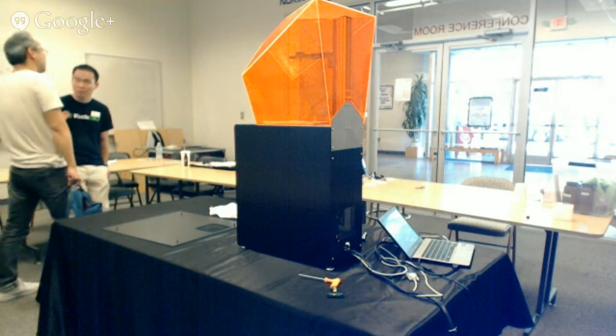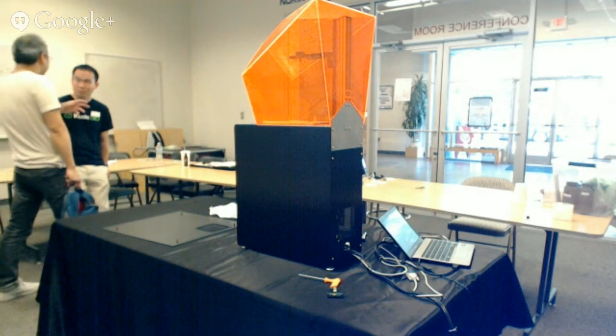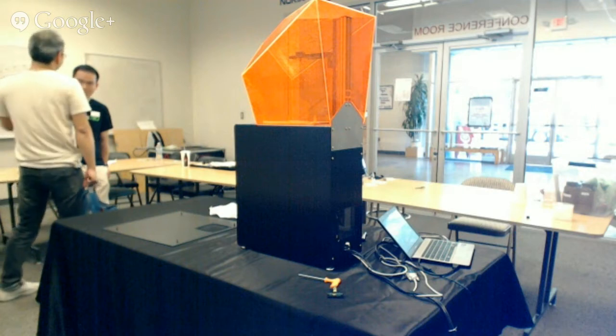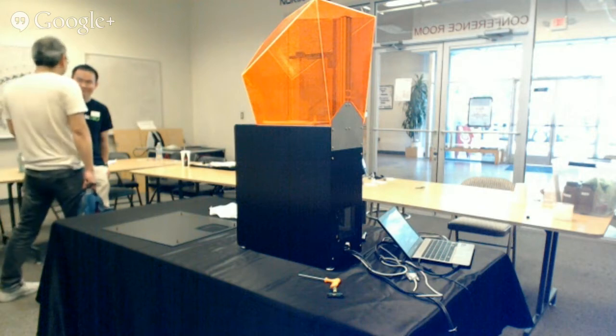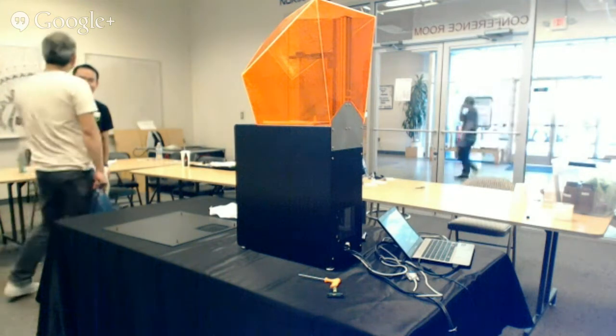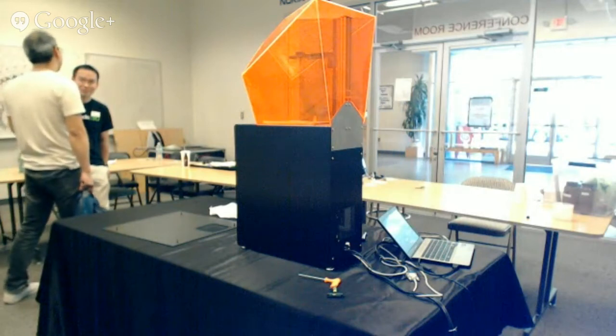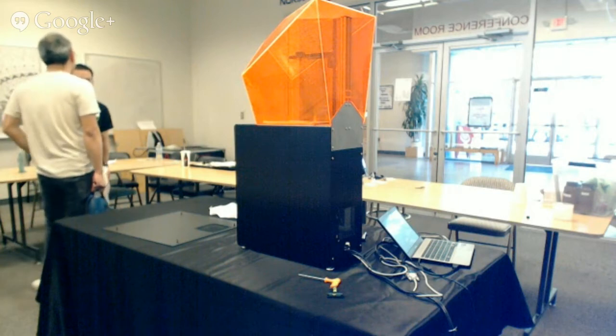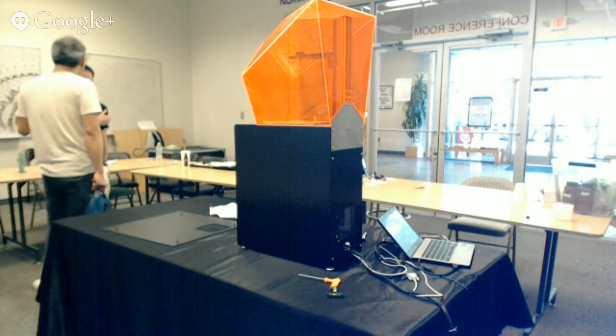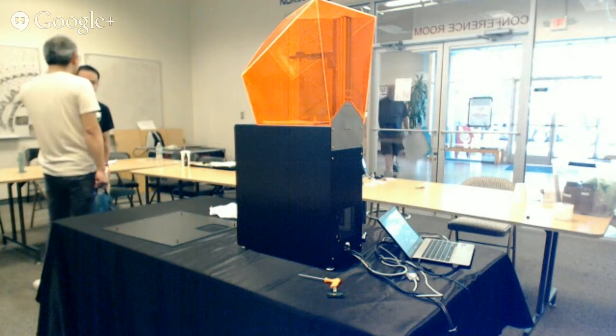Now, if I'm going between 37 and 50 microns, and I know from talking to John that you already had the projector set at the correct distance. Yeah. Now, the focus of the projector, do you have to adjust that focus, or once it is set, it's set? Because I've seen your competitor, you have to focus on the build tray and then targets to try to focus to. Well, there's a calibration grid. You calibrate, the calibration grid is focused against the build plate. Right. The build plate is set at the level of the vat. Right. And you focus against that.